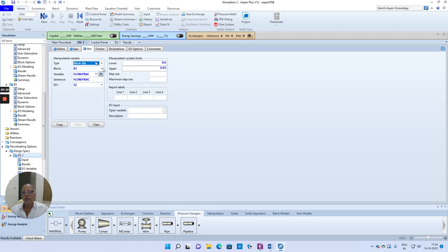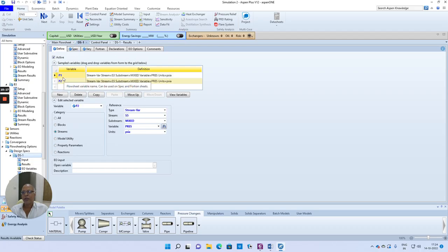In the same way, of course, if you want, you could have defined delta P1, the pressure drop in pipe 1, and delta P2, the pressure drop in pipe 2. But the moment you want to describe that as a pressure drop, it is not a stream variable. You will have to select that as a block variable because pressure drop is associated with the block pipe, and equate delta P1 to delta P2 like what you did with respect to P1 and P2. Whether it is delta P or P1 and P2, both are the same because the input pressures are the same.